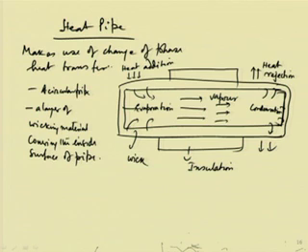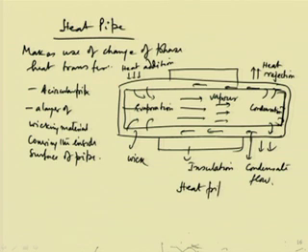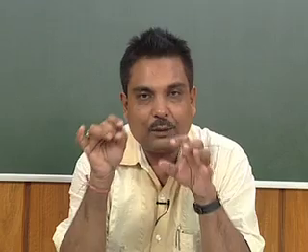It will come to this end, where the heat rejection takes place and it will be condensing, and then the condensate will come in this direction. This is a condensate flow. This is typical of a heat pipe. Okay. So, at one end it is getting evaporated, and at another end it is getting condensed and coming down. So, there will be a heat exchange.